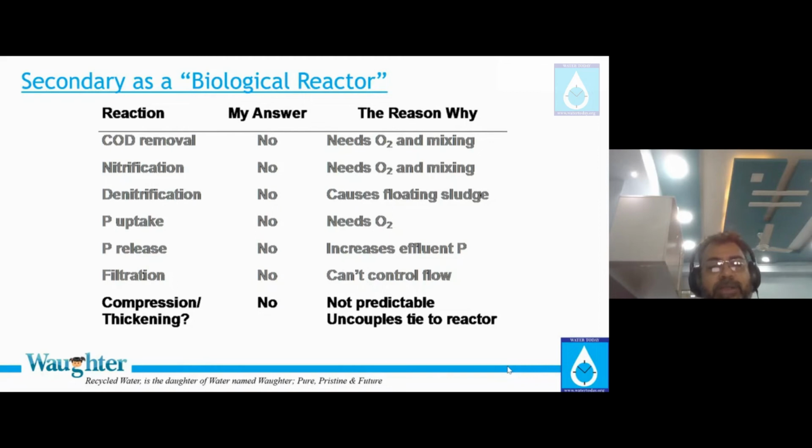P uptake? No, because P uptake needs oxygen. P release? No, because it increases effluent P. You cannot design for P release. Filtration? No, you cannot control the flow. And compression and thickening? No, it is not predictable, because it is coupled to the reactor.